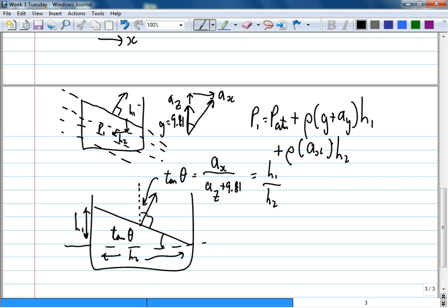Alright, so that's when you have a container. What's the container doing? Accelerating. The net effect is just like rho GH, except your G is no longer just upwards, but upwards plus whichever direction the container wants to accelerate in. Okay, so you have an isobar.